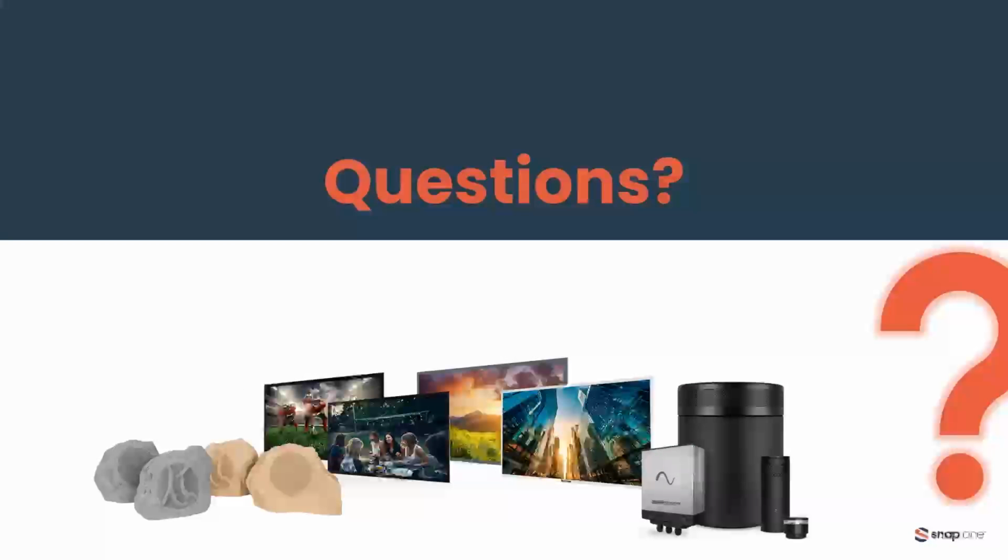Let's see here. What if you are in a Sonos ecosystem and want to use a Sonos amp? It has a left and right output. Since it's outdoor and you want an even listening experience, how do you connect the speakers for a typical backyard with 2 to 4 speakers? Yeah, so I think in this case, Paul, you would use the Sonos amp. You'd have to use it with our 8 ohm speakers, and you'd be limited to, like you're suggesting, one speaker per output, or potentially paralleling 2 speakers per output and getting 4.